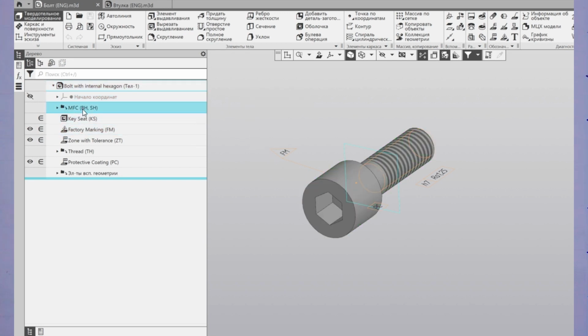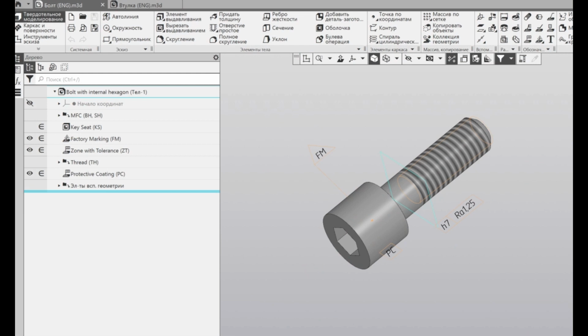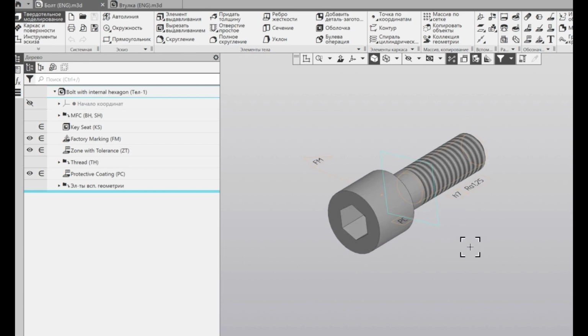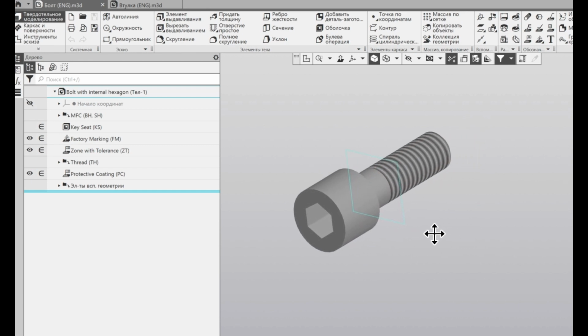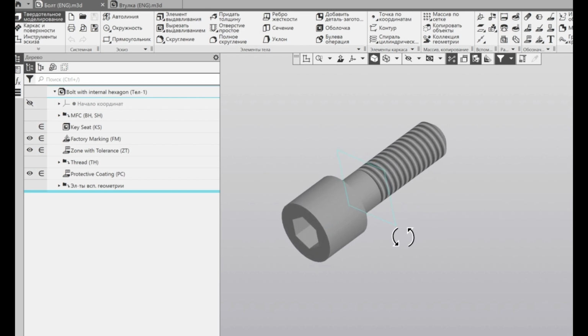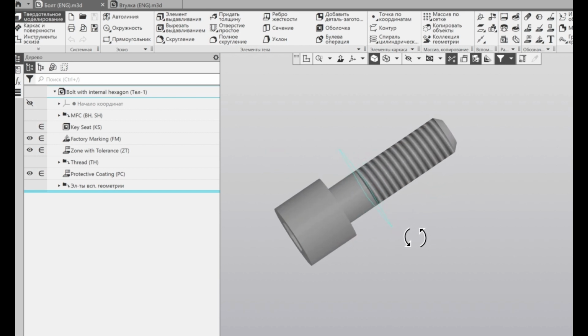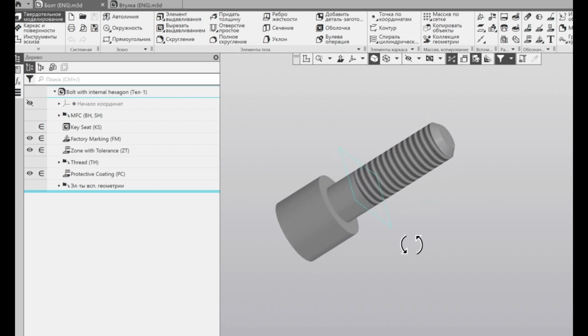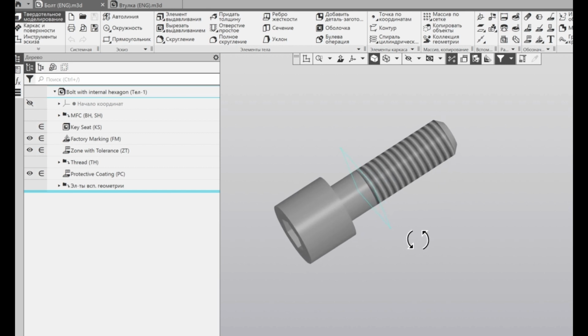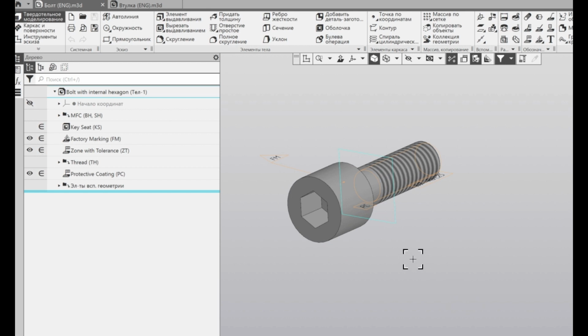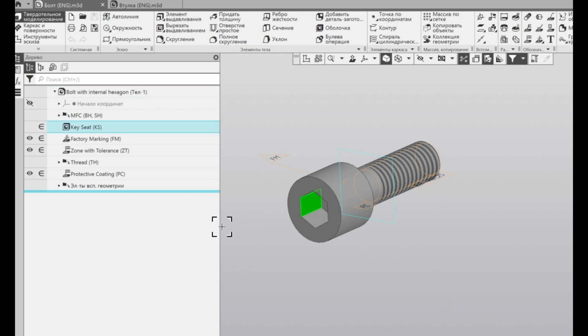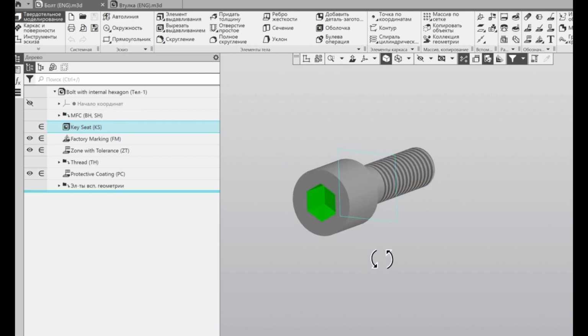Depending on the possible basic manufacturing technology of this bolt, such as powder technology, milling, casting, or upsetting, various combinations of basic technology with additional operations will take place: electro-erosion, manufacturing of the bolt head hexagon key seat, threading, thread rolling, laser marking, etc.